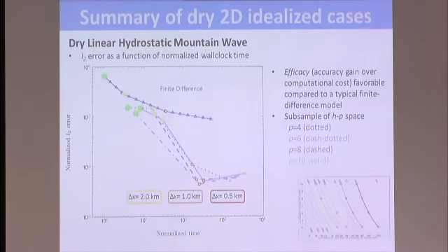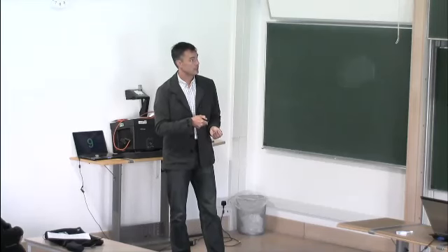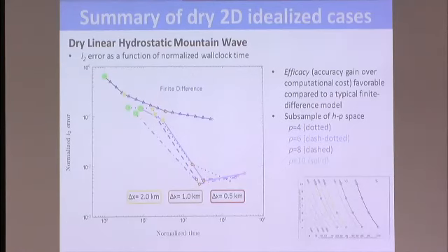If you now look at the spectral element results, which are these lower curves, and let's just focus on, I'm plotting 4th, 6th, 8th, and 10th order. You can see that this is 10th, 8th, 6th, and 4th order. They're kind of bunched together, but the idea is if you actually happen to have resources and you invest them into your model, and you can run your model, you will get payback. So you can definitely get an order of magnitude increase in accuracy. But at some point, again, it levels off.